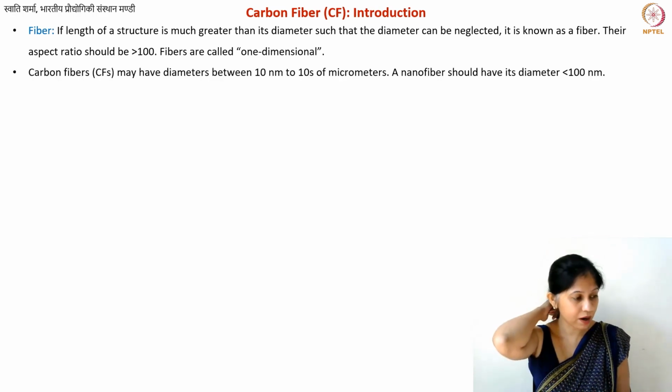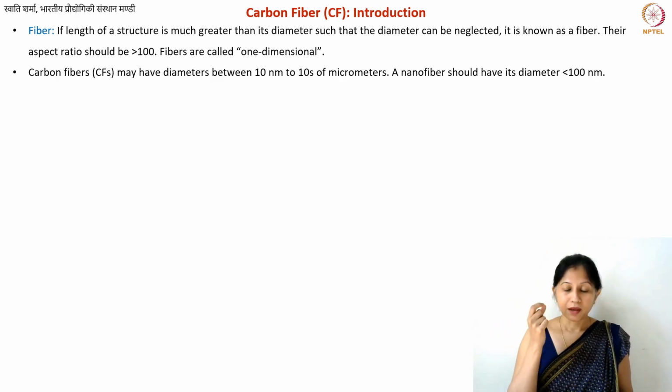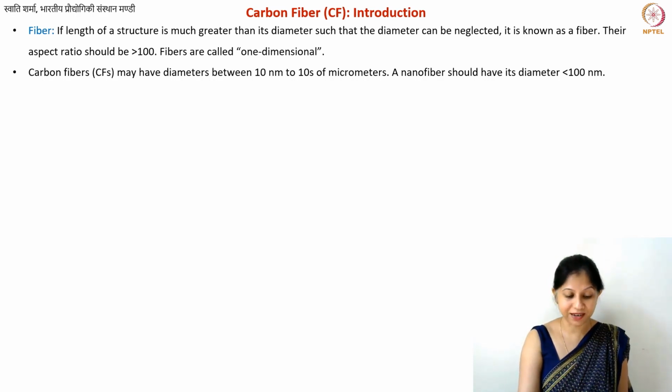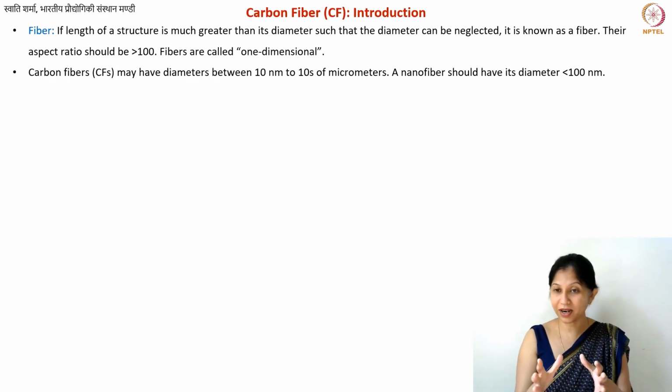But what are carbon fibers? Well, they are fibers from carbon, but you know that carbon is hard and brittle, and you cannot directly pull fibers out of it. So you also know that there is one more method that we use for making industrial graphite structures. We also use it for making industrial bulk glass-like carbon materials. We shape the polymer, and then we carbonize it. We do the heat treatment.